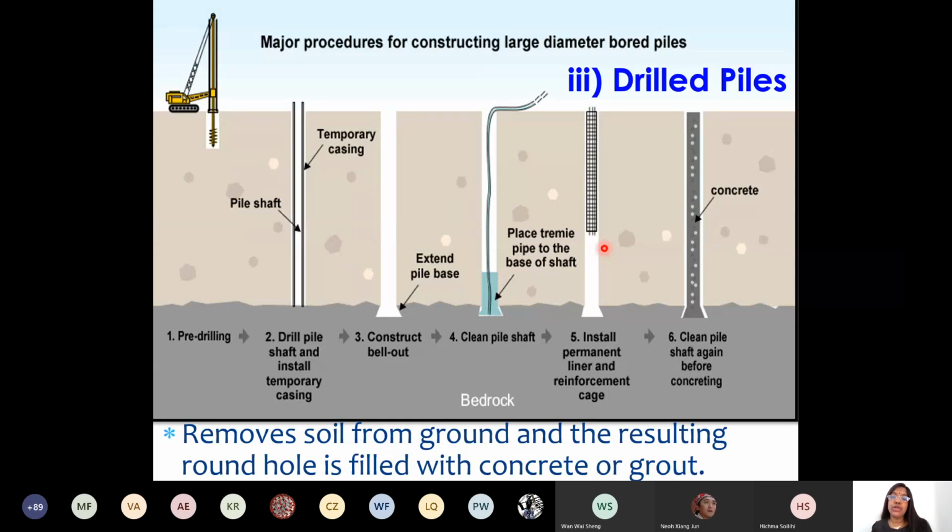Okay, and then wherever it is a very cold region, where the marsh condition is there all through the year, the climate is very cold, and the RH value is always high, then you can go for concrete, because there are chances of rusting and problems in steel piles. Also where it is always lying in water conditions, river conditions, or supporting a bridge or a culvert, concrete is preferable, if the stress is good enough for a concrete pile, you can go for it.